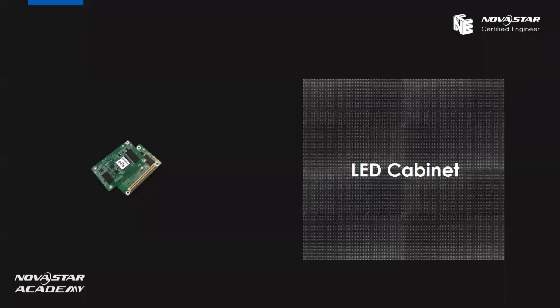As I just told you, normally there is only one receiving card in each cabinet, because without a receiving card, the LED cabinet cannot show any image. But with the development of this industry, the pixel pitch becomes smaller, so the resolution of the LED cabinet becomes bigger. In this case, one receiving card is not enough. Our LED cabinet may have two receiving cards inside.